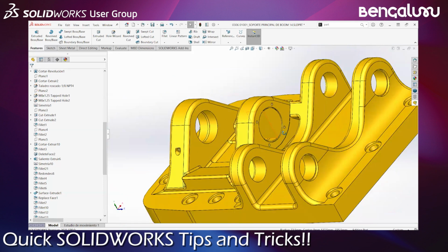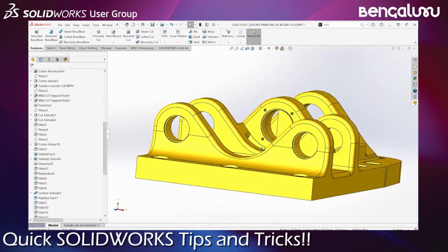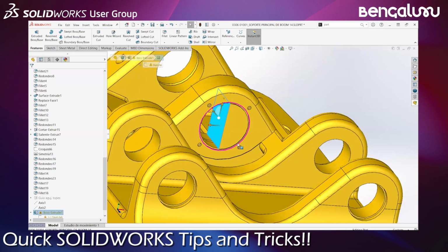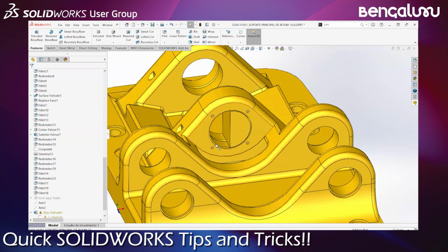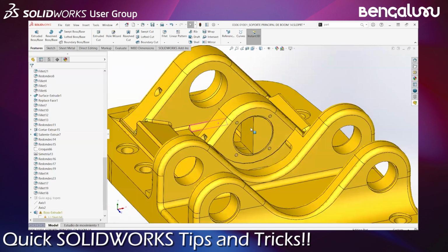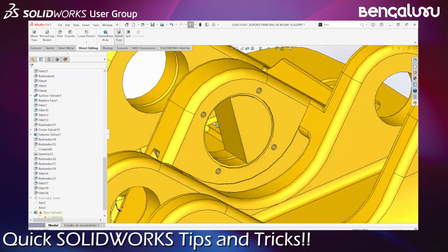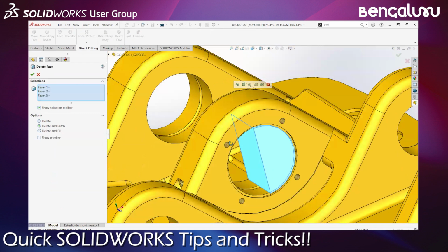Now, the next thing that I would like to show you is that in this particular hole you have additional material that has been added right here, and I want to remove it. When I ask any designer to remove it, the first reaction would be to create a circle and then do a cutout. But what you can rather do is, under direct editing, you have something called delete face. I select this command and select the faces that I wish to remove.